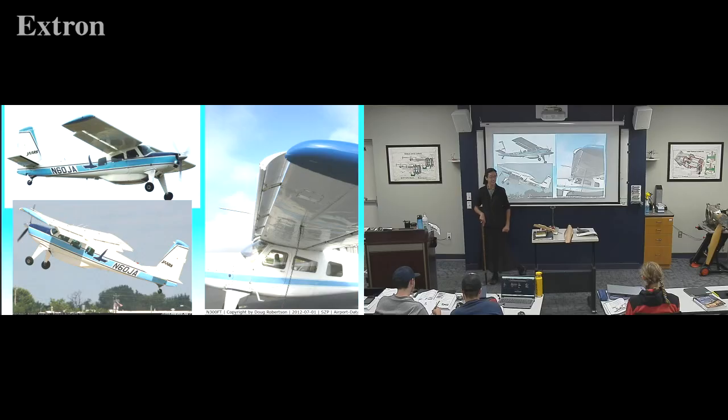Oh my. It's to keep the airflow over the top. Perfect. So to help keep that laminar airflow. So this helps with that. It also, what's it doing to camber? Increasing it with the front, just extending that whole wing so we can have a whole lot more lift going on. But slats